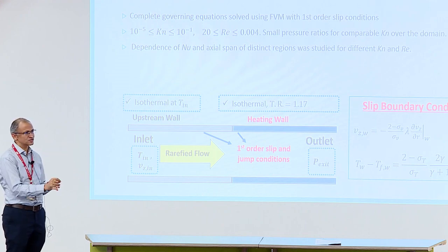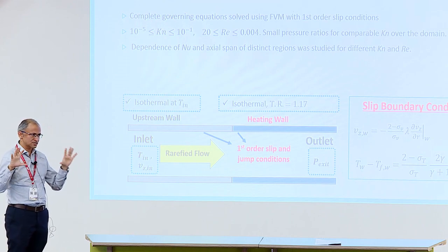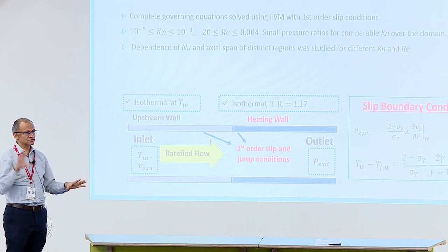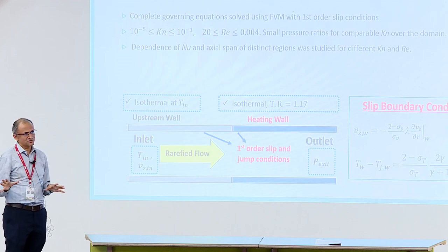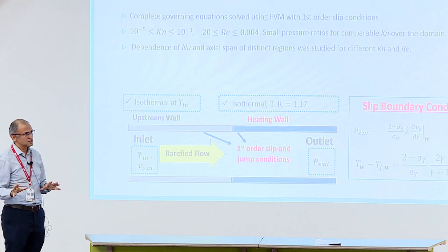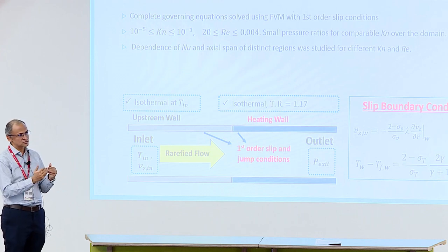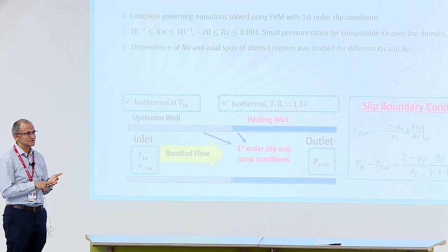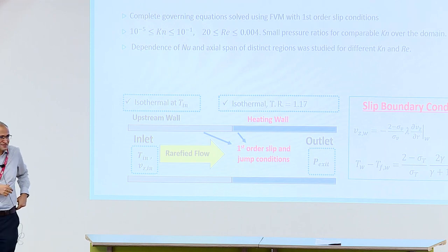One is worried about, if I put helium in there, this coefficient. From whatever data collection and analysis we have done, in a survey paper we have written, you can see that a monatomic gas and a diatomic gas will behave differently. Whether a triatomic gas will behave differently from that is not clear. So helium and nitrogen, yes, I do expect a difference in behavior. With respect to surfaces also, whether it's copper, glass, or platinum, there is also some amount of dependence in there.